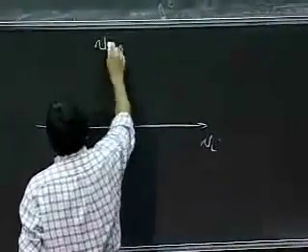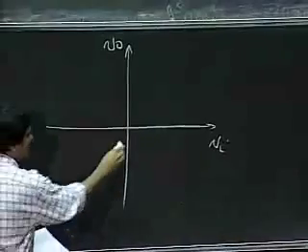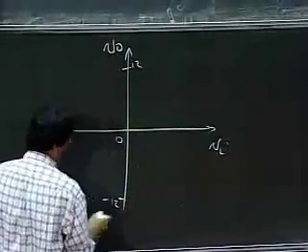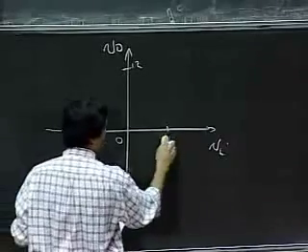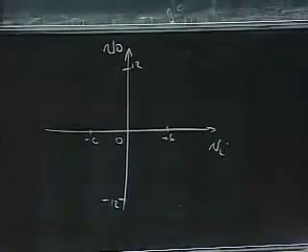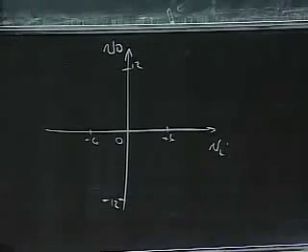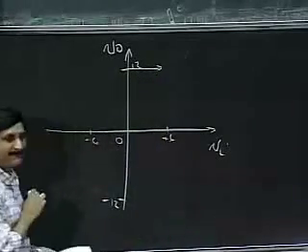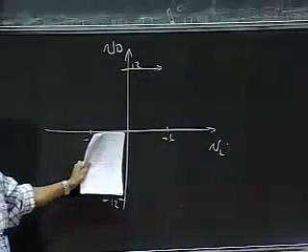So this is Vi. This is V naught. This is 0. Let's say this is 12, minus 12, minus 6, plus 6. Okay, let's plot that on the screen and see what it looks like. As I told you, the output was at 12 volts to begin with, and my input was at 0.